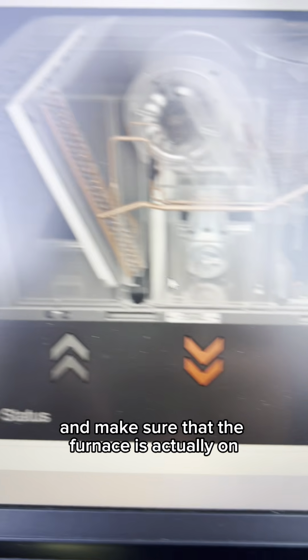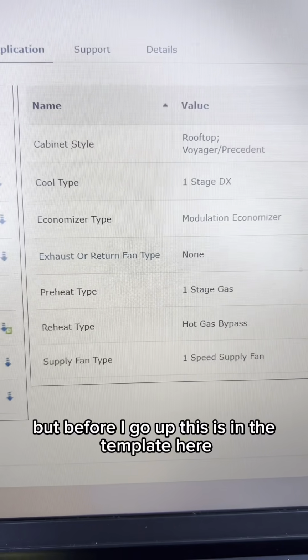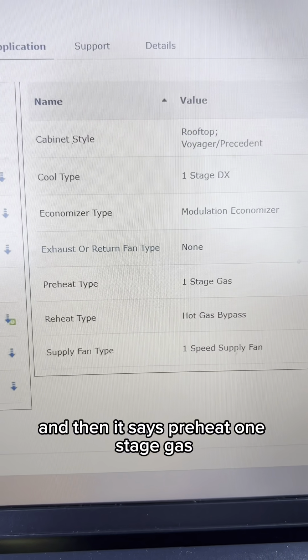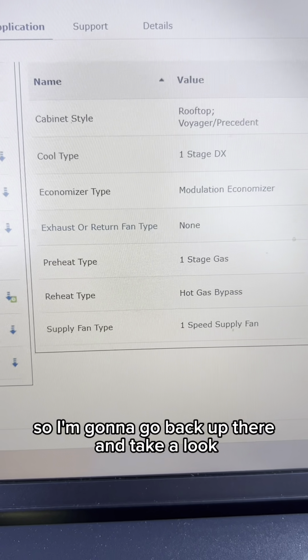Now I'm going to go up on the roof and make sure that the furnace is actually on and that we're not just running a compressor. But before I go up, this is in the template here. You can see it does say 1-stage DX, modulating economizer, and then it says preheat 1-stage gas, and then reheat type hot gas bypass, which is for the dehumidification. So I'm going to go back up there and take a look.